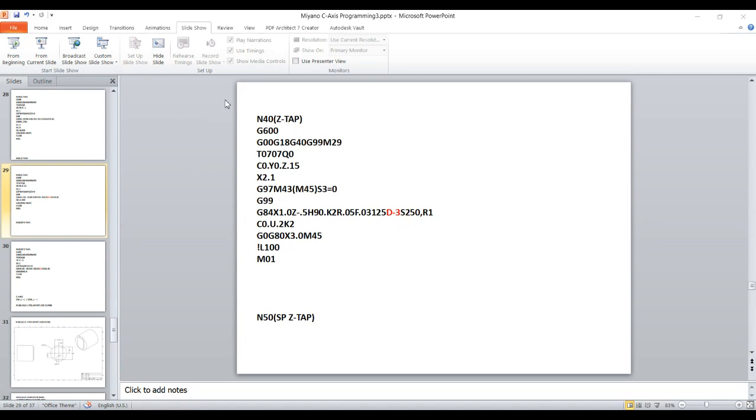Okay, please continue. Now we're moving on to the spindle tapping. The important thing is we need to stop the spindle. Lots of programmers rotate the spindle before starting the G84. So stop the spindle and it will give you less headache. With G84, now we are doing spindle 1, that's why I have a D1 here. And that's about the drilling cycle and tapping cycle.